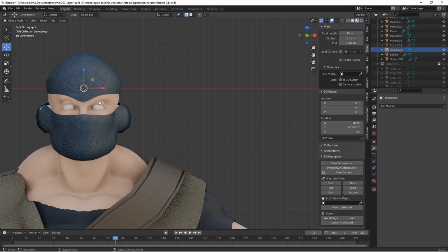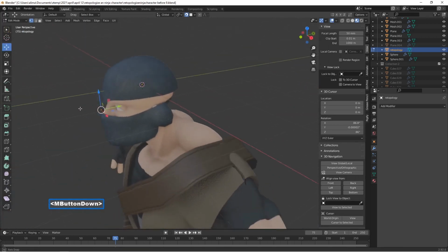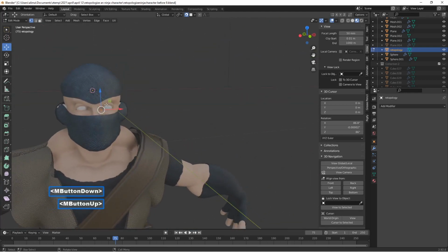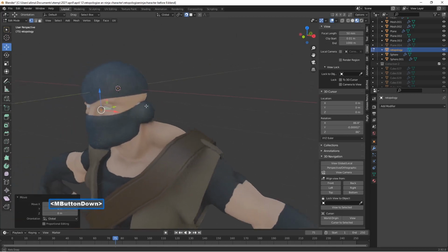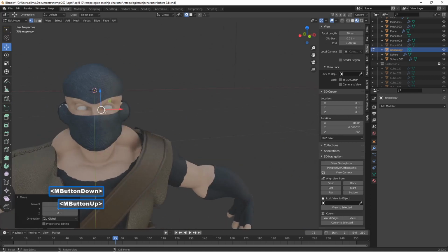All right, so with the snapping back on, as soon as I press G, I'll show you this. I'm going to go to the upper left, go to edit mode, right? So when I rotate the view, you can see the vertex is in front of the face, right? What you want to do is line up this vertex so it's, by how you're looking at it, aimed to where you want it to stick to. So when I press G, which I haven't done yet, but I'm about to, I press G. Now I left click. Doesn't look like anything happened from this perspective. However, when I hold the middle mouse button, you can see now that vertex is actually sticking to the face, which is what we want.